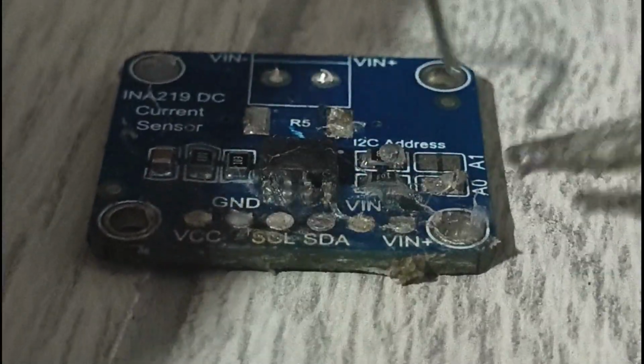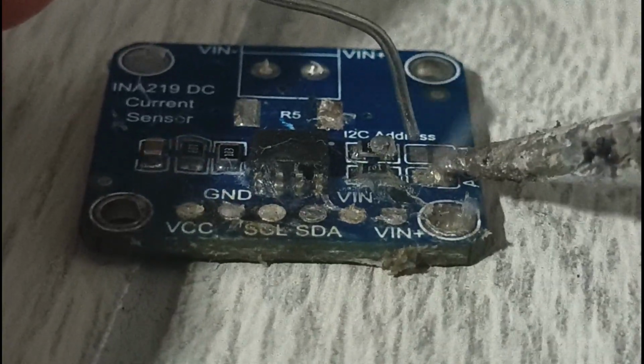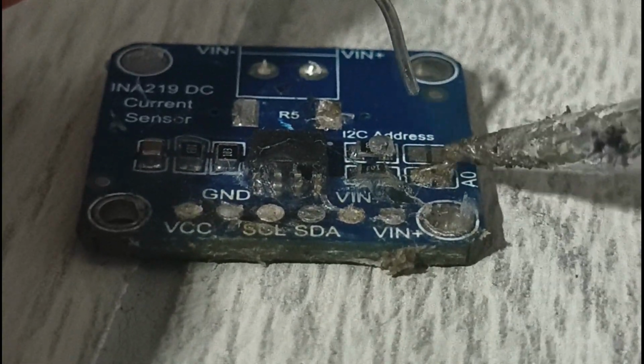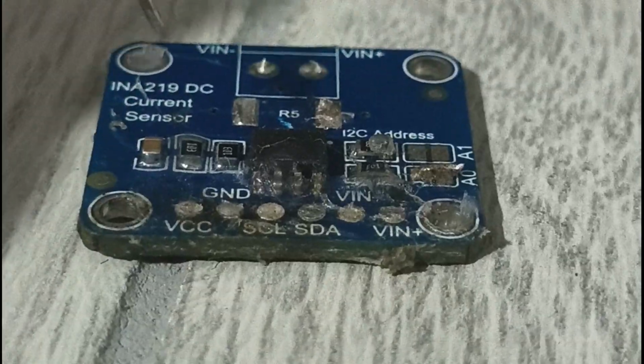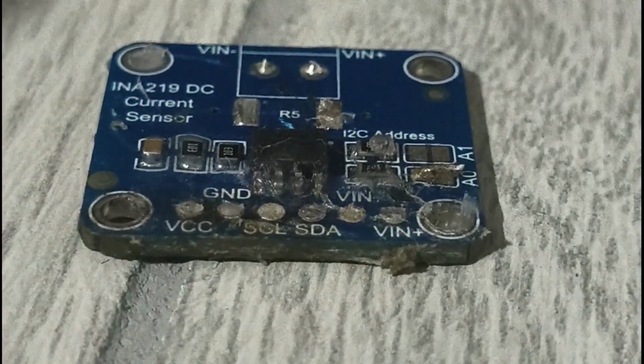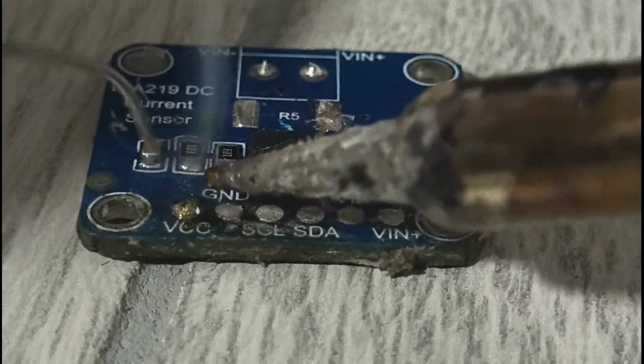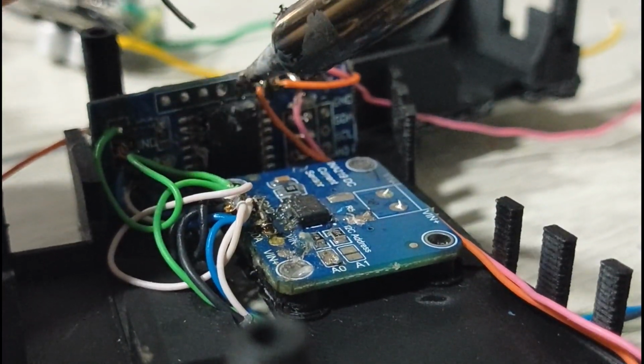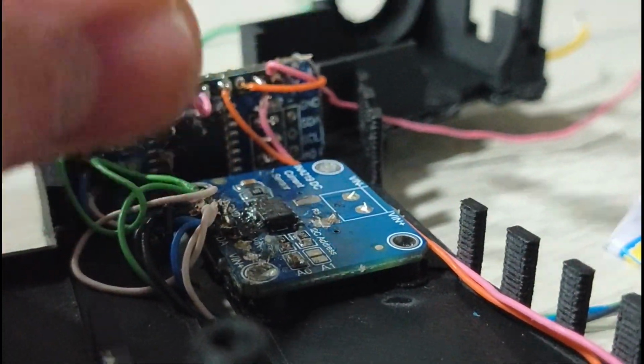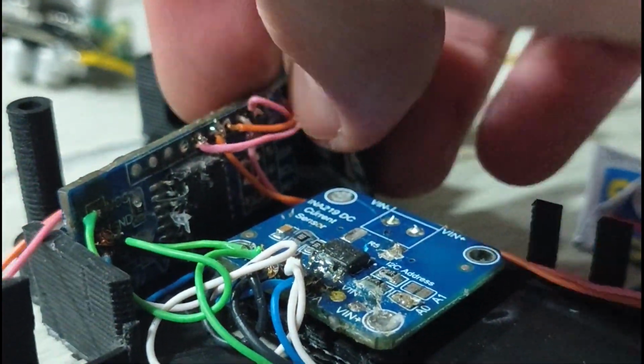So this is your INA219. You'll need to remove the screw terminals and any shunt that may be installed onto the board, because we're only reading voltage, and the code has been adjusted to read without the shunt. So we'll connect that to the I2C system, remove the screw terminals, set the address 0 pin, and remove the shunt, and everything should work just fine. We'll also need to connect it to the voltage input from the battery system to monitor the voltage of the robot.